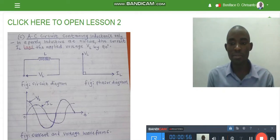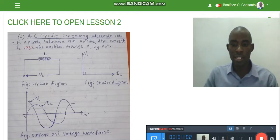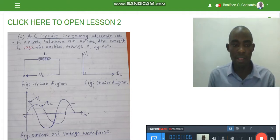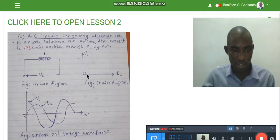But like we have said before, in a series circuit, current is taken as the reference. Whenever you are drawing the phasor diagram, the current is always taken as the reference phasor. Therefore, the current is drawn on the horizontal scale. Look at this phasor diagram. This is our phasor diagram, and this is our circuit diagram.